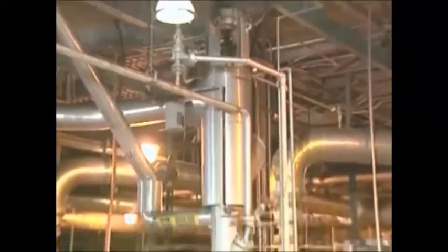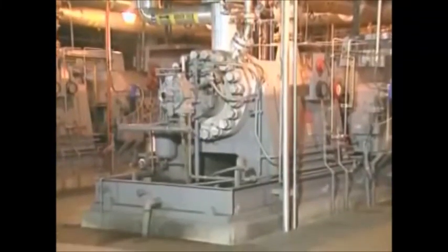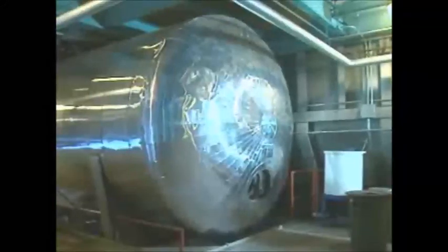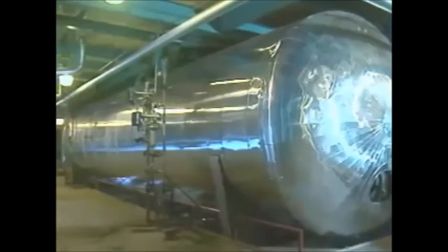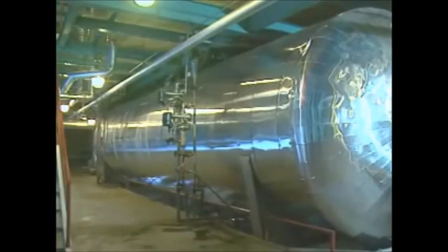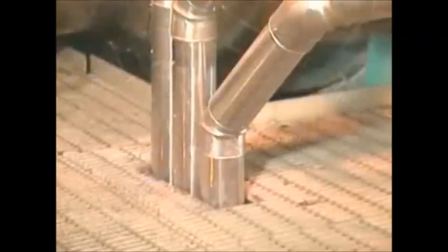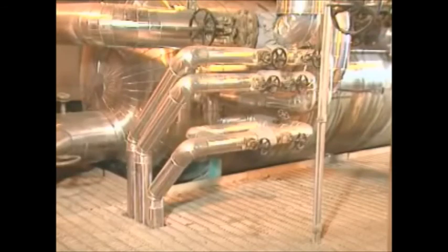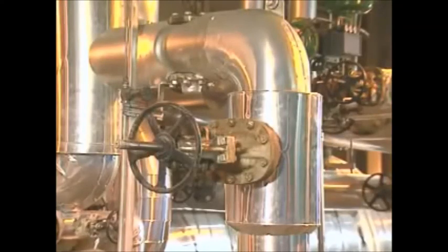For example, if boiler demand increases, the boiler feed pumps begin pumping feed water from the storage tank at a rate that's greater than the rate at which condensate is being fed to the tank by the condensate system. The hot surge tank supplies enough feed water to meet the increased demand for the short time it takes for the condensate flow and the feed water flow to become equal again. Both deaerators and hot surge tanks often have additional connections. Examples are connections from the higher pressure feed water heater's cascading drain system and connections to the vent system from the high pressure heaters.